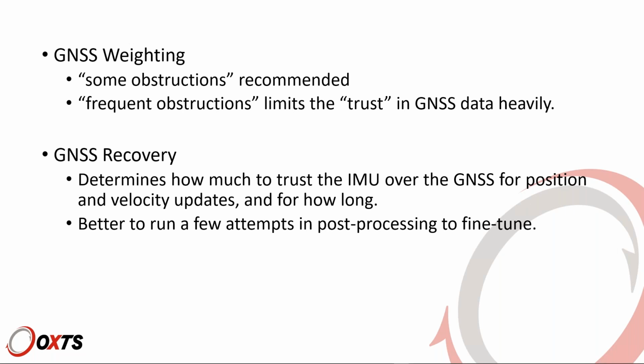The best way to do this is to run a few attempts in post-processing to fine-tune the exact number of updates that will be needed before the system believes the GNSS again. Because there is no one size fits all in this case. It would pretty much depend on the specific situation. So if you want to use it, I would recommend you fine-tune it in post-processing.